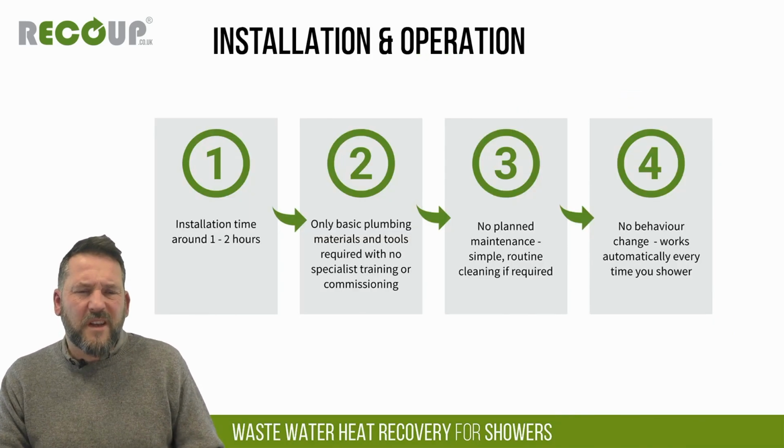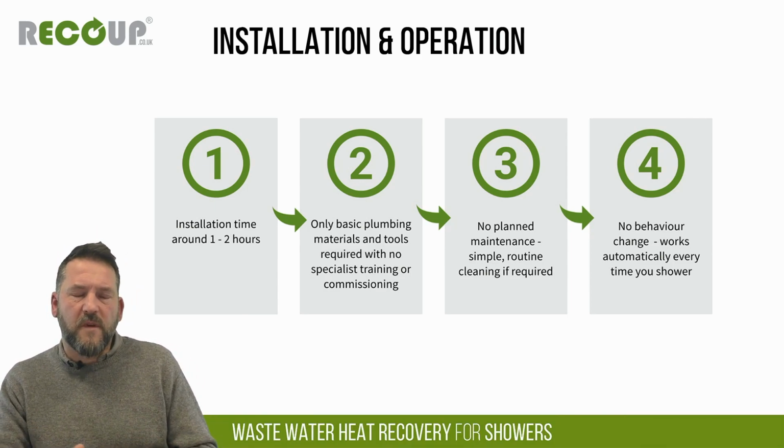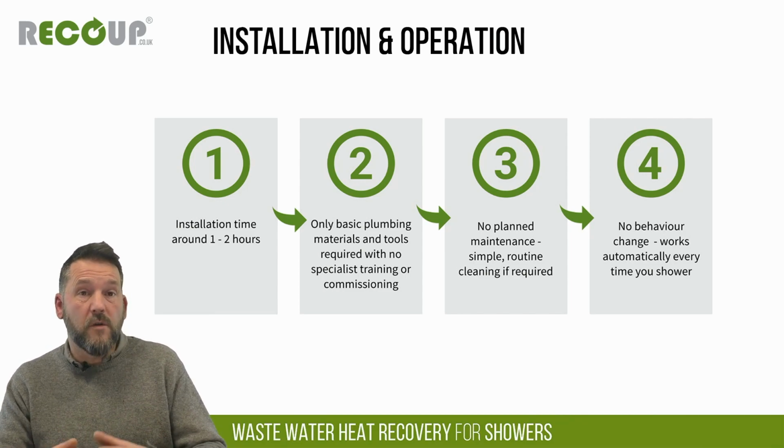Just a quick note on installation and operation, because it really is very simple. It's a summary of what we talked about here. First fix installation is generally around 1 to 2 hours of extra plumber's time, so relatively quick, relatively easy. Only basic plumbing materials and tools are required, so there's no specialist commissioning, no MCS accreditation or anything along those lines required. It's your jobbing plumber, your installer, that can do this.